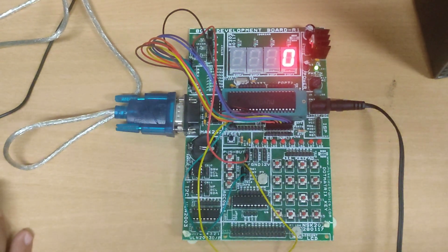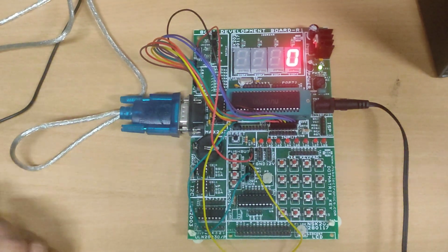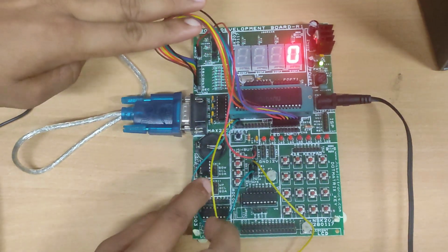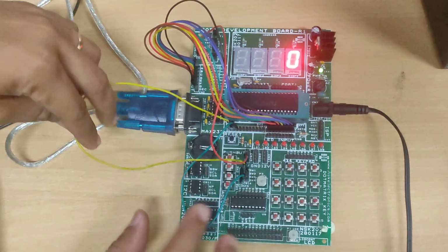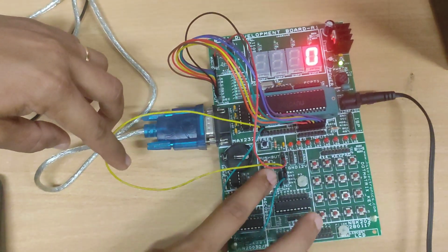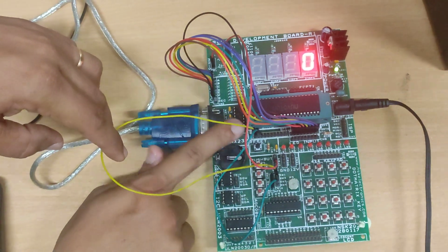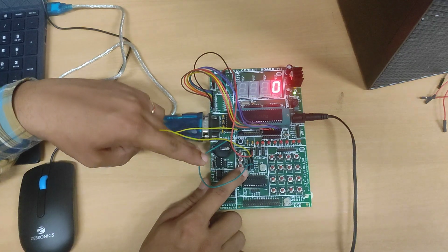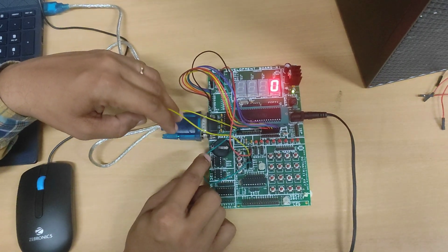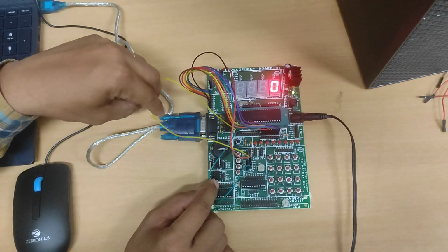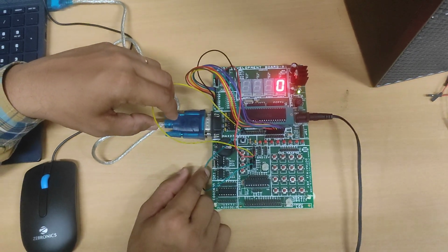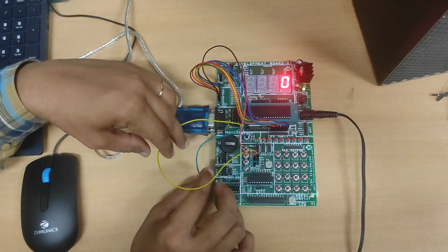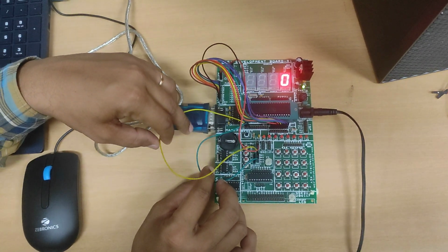Hello everyone. In this presentation we are going to understand how to interface two switches with a microcontroller. Say for example, here we have one switch, where a yellow color wire is interconnecting the switch with P2.0 of the microcontroller, and the green color wire is interconnecting another switch with P2.1. So P2.0 is connected to one switch and P2.1 is connected to another switch, which can be used in bit set reset mode, which is one of the special features of the controller. All the four ports are bit set resettable.